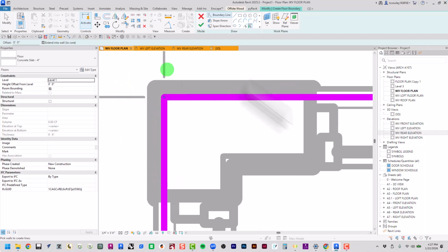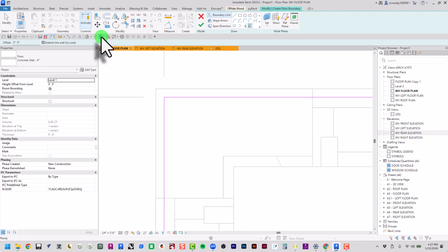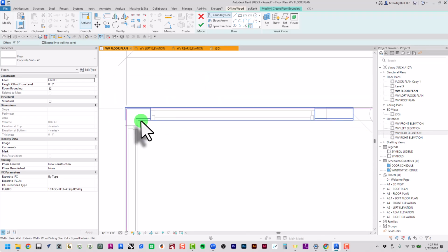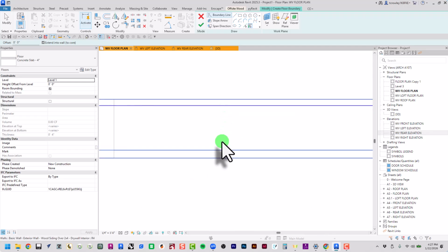When I'm talking about layers, I'll show you what I mean. This is a little tool called Thin Lines. I click Thin Lines. What it'll do is take away all the line weights and hierarchy of each of these lines of the drawing and just show me very thin lines for every single component, including our walls. So this is one of our walls. Let's look at it from over here. And this big chunk in the middle is our 3.5 inches of structure, our 2x4.